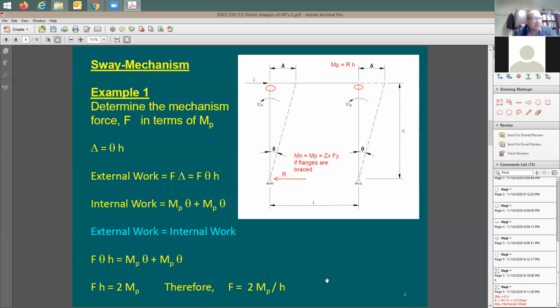Can I give here some symbols? I'm going to say the length, center to center of this, is going to be equal to L. The height of the frame is going to be equal to H. Boundary conditions: I'm going to have here simply supported, which means a hinge and a hinge on both sides, or a pin support. The top, I have here fixity between the column and the beam. Therefore, I'm going to be able here to develop this moment. When you push it, this can be developing here some moment.